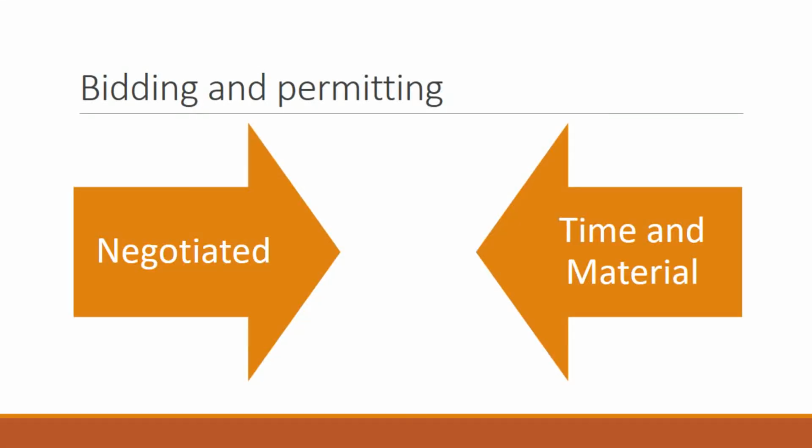So moving on to the second subphase, and this is bidding and permitting. The process for soliciting bids and obtaining permits is the heart of this phase. Now, today's fast-track projects frequently involve simultaneous permitting and bidding, and it is advised to deal with any site, zoning, and public hearing issues as early as possible in the design process. The various trade permits, such as HVAC and electrical, can typically be submitted after the successful subcontractors let individual subcontracts, even though many regions only require a general construction permit.